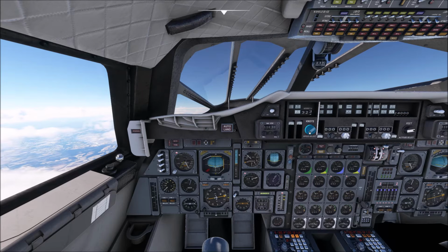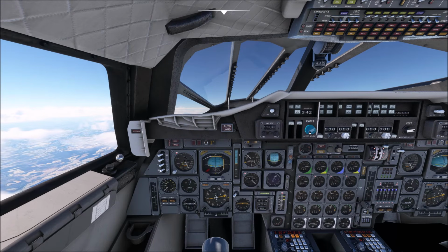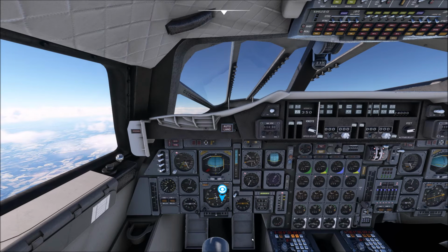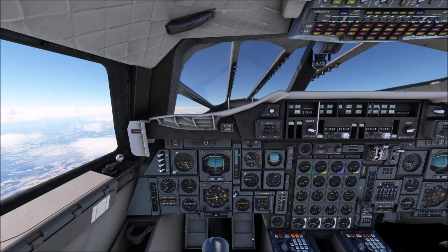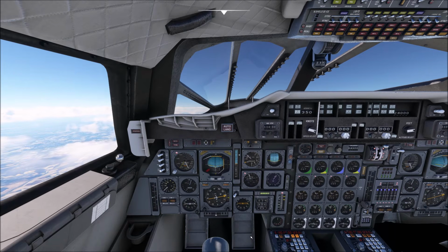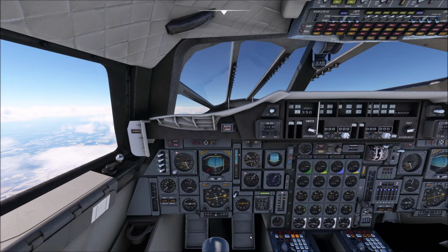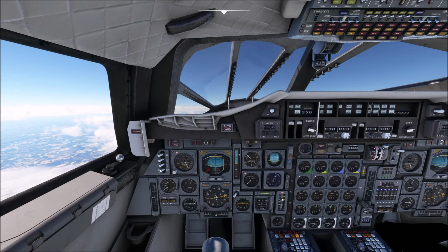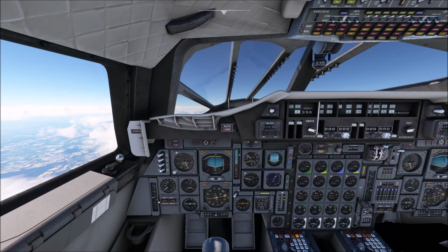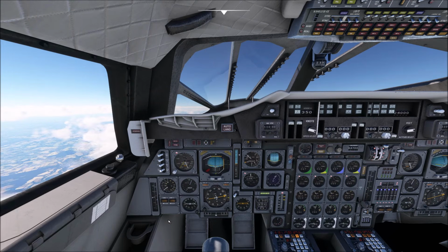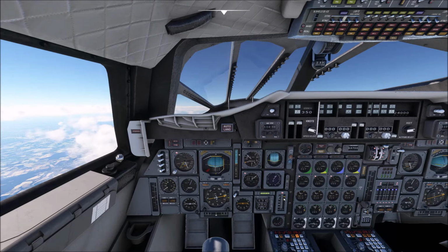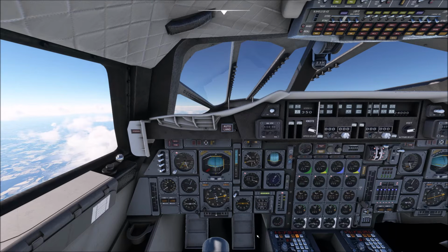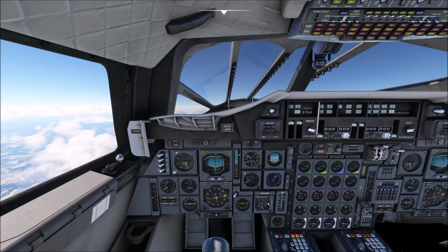Push the speed up again now. 350. CFG is balanced, looking good. Just over 5 degrees angle of attack, that's acceptable. This is affected by CFG as you sweep it further up. You can still make New York without doing it, but it'll be much more efficient, Concorde, if you do make the effort to move the fuel.